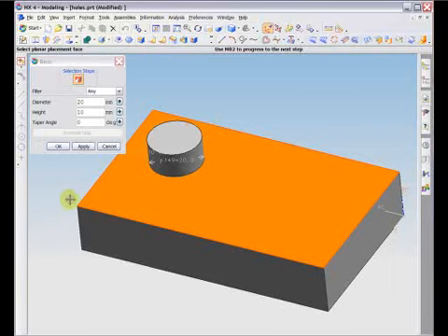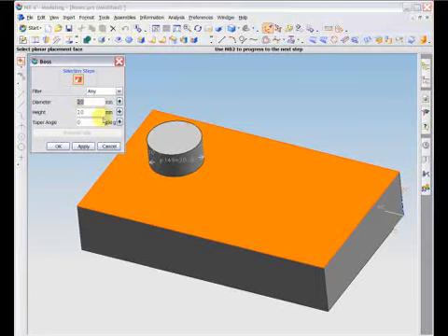If you select an absolute datum plane for the placement face, and more than one solid is present in the part, a target solid selection step becomes available, which you must use to select a target solid for the boss. Bosses cannot be created independently of another feature. You must then simply enter a diameter and height for the boss.